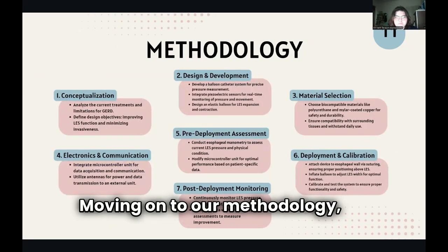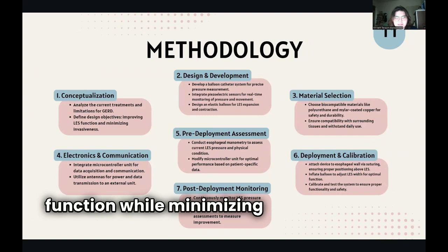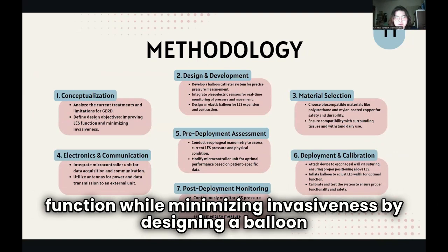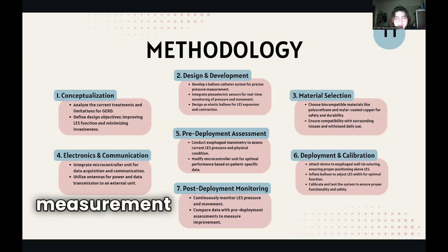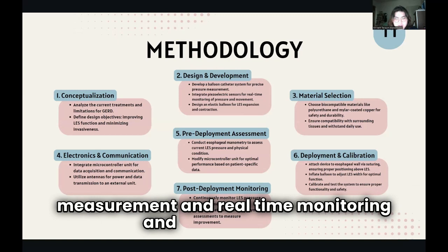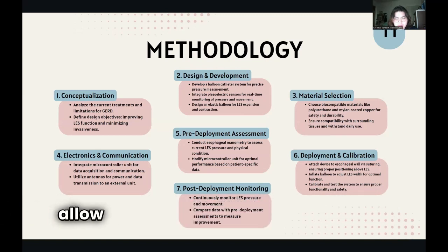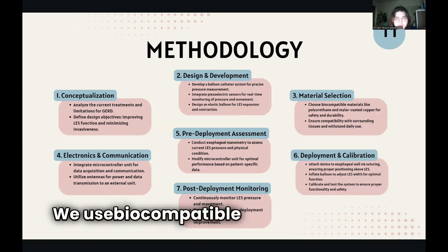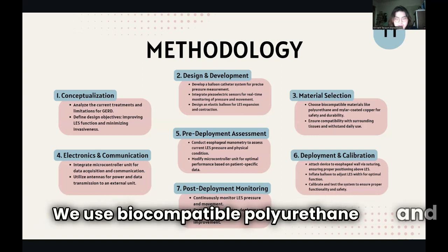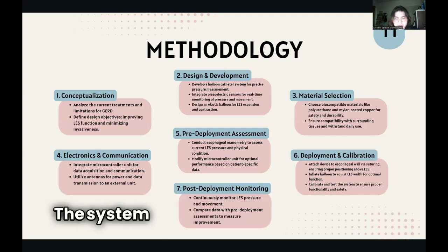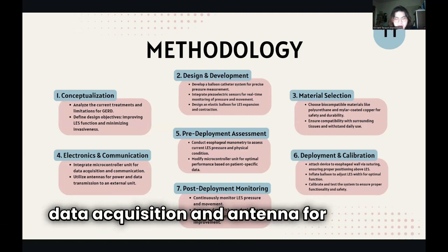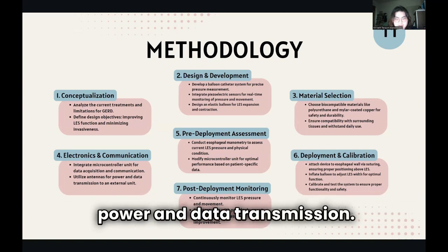Moving on to methodology, we improve LES function while minimizing invasiveness by designing a balloon collector system with a piezoelectric sensor for precise pressure measurement and real-time monitoring. An elastic balloon allows for LES expansion and contraction. We use biocompatible polyurethane and Mylar-coated copper for safety and durability. The system includes a microcontroller for data acquisition and an antenna for wireless power and data transmission.